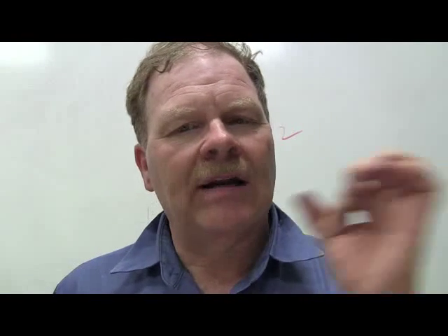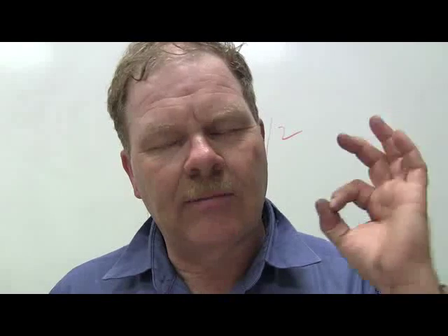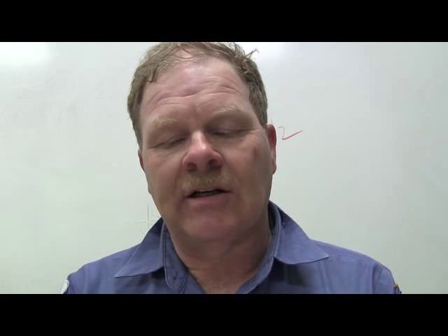These block style ones actually have a big hole and a little hole. The big hole is where the temperature is measured that causes that variable orifice to change, if it's that expansion valve. All right, so basically you're going to put that on the evaporator inlet because it needs to control that.